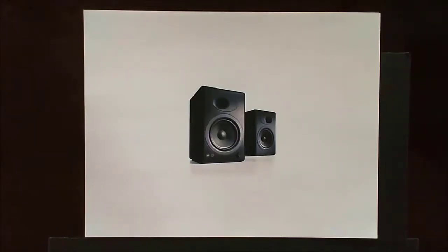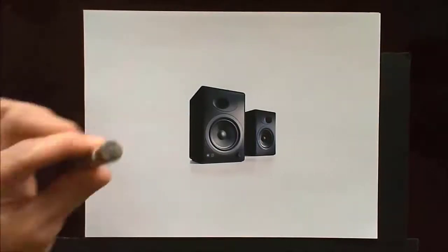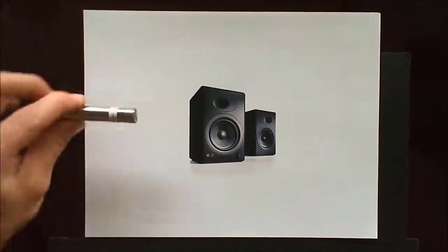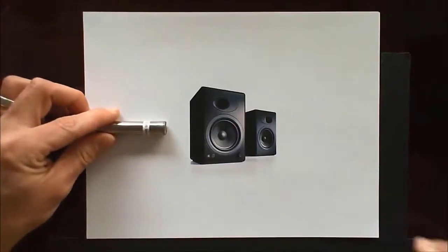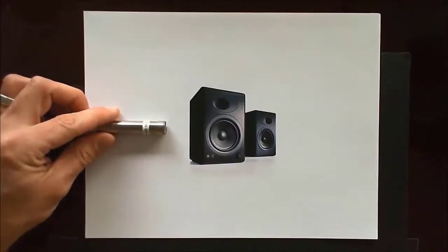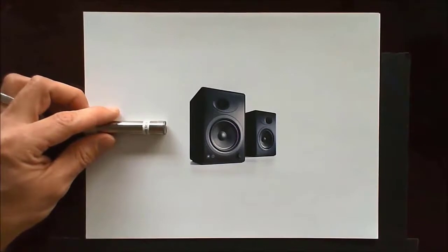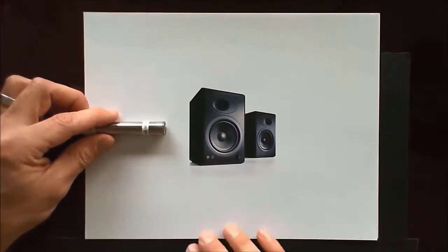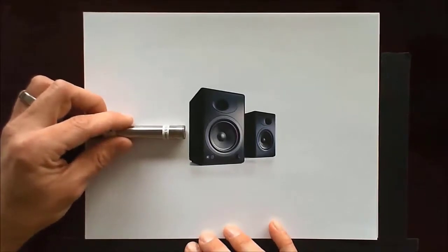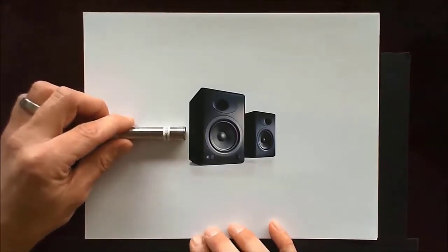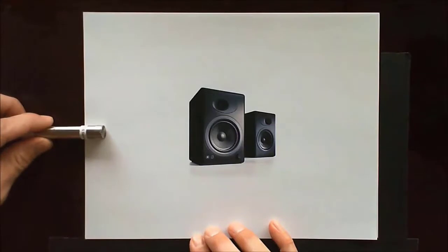Well, if you're familiar with sound pressure and measuring sound pressure levels and reporting them in decibels, you might think, okay, well, I can just take a half-inch pressure microphone and place it near the object and record how loud it is and report that sound pressure in decibels. But there are some things to keep in mind with sound pressure, such as if I measure the microphone right here next to the speakers, am I going to get the same answer as if I measure back here?